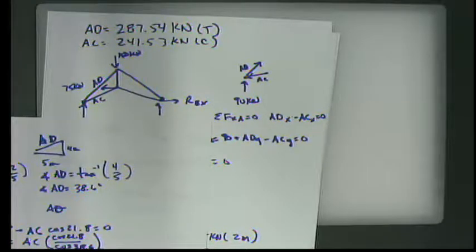Exactly, yeah. What's really happening is, if you think about it, joint A can't bear anything in the horizontal direction. So everything is being transferred elsewhere in order to keep that load. This sort of truss is more or less called a scissors truss, and it's a kind of truss that you would put in for a cathedral ceiling. Except on the cathedral ceiling, it really is anchored at both points, and then you have to reinforce the heck out of it right here.